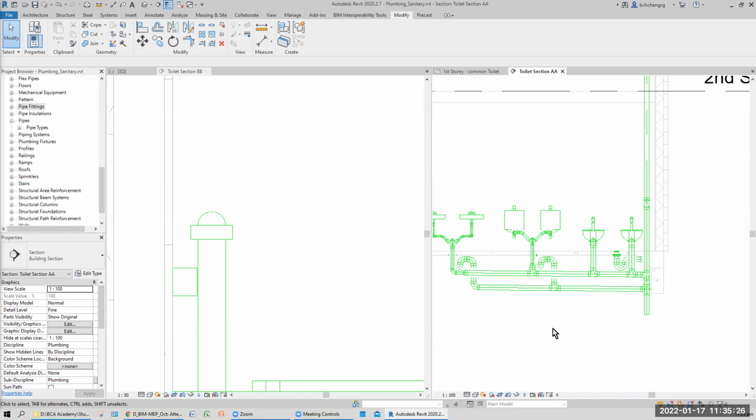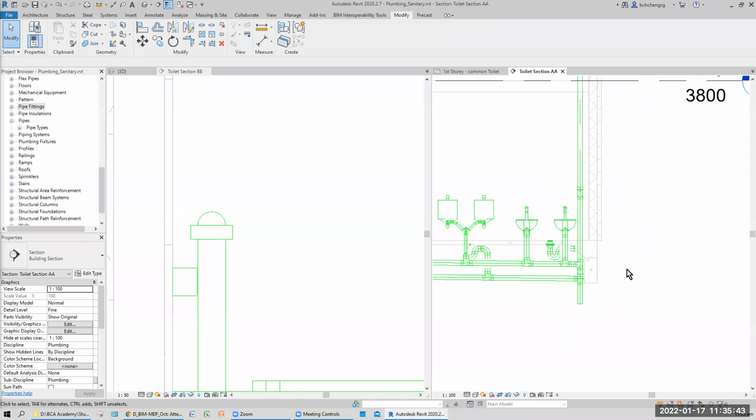Things with pressure, for instance your cold water piping, the supply, we don't need to have any slope. It's always horizontal, vertical. Why? Because they are pressure. So for pressure pipe, of course, it depends on the material used, because with different materials, some are good, some are bad. Sorry, let me rephrase. I did not mean bad.